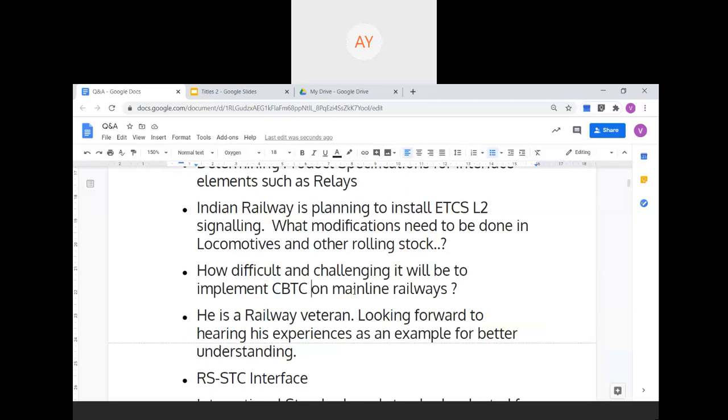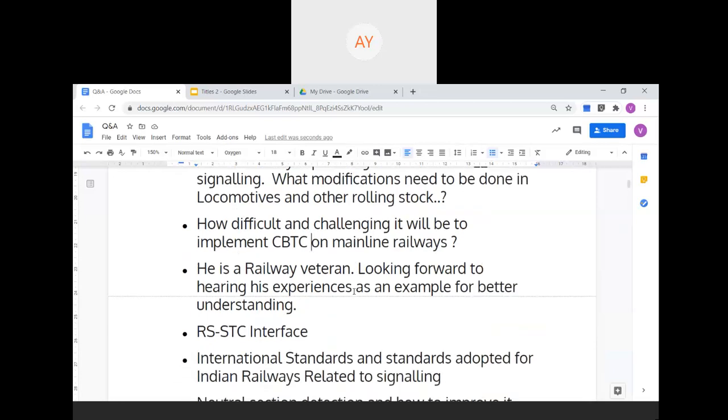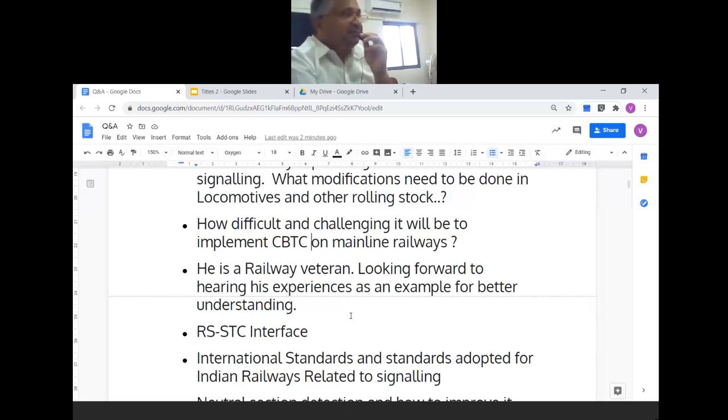And you install odometry systems and interface with the braking. That is the most challenging part. In fact, you have to put a lot of electromagnetic solenoid valves on the brake pipes and the main reservoirs, and because that is a safety system of the rolling stock, when you interface there, it has to be done in a very defined and approved manner, where both the subsystem owners come and discuss and design that interface. Even the BTM antennas have to be mounted below. I think that is the easiest part.